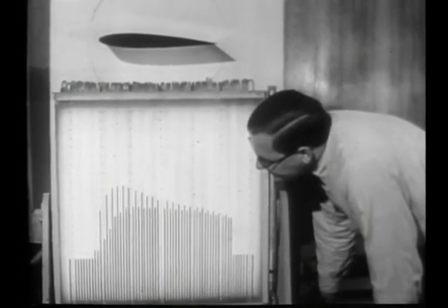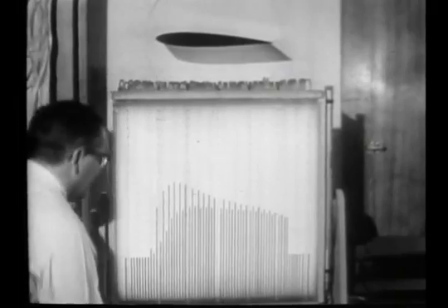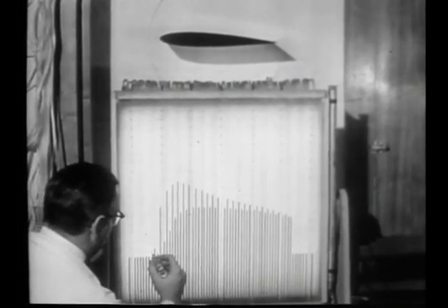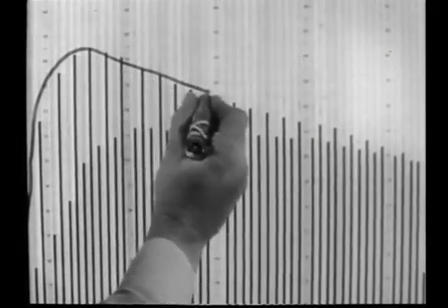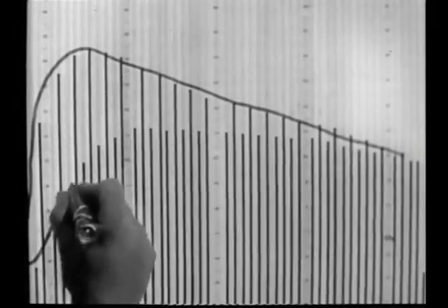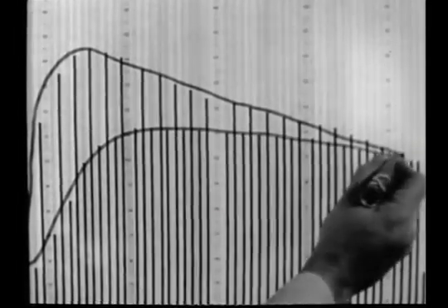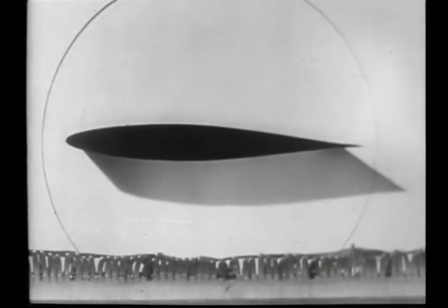For a given lift, we get a greater length of laminar flow by modifying the pressure distribution through a change in the airfoil shape. To demonstrate this, the lift of this profile at this angle of attack will be indicated by the area of this pattern drawn on the manometer. Here is another airfoil, adjusted to give the same lift. It has the same maximum thickness as the previous one, but further aft, close to the mid-chord point.